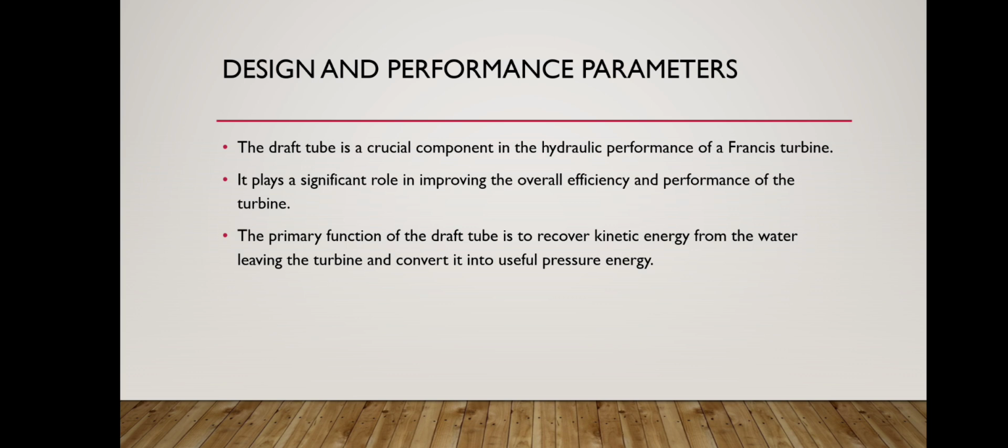Design and performance parameters. The draft tube is a crucial component in the hydraulic performance of a Francis turbine. We all know this, and it plays a significant role in improving the overall efficiency and performance of a turbine. The primary function of the draft tube is to recover the kinetic energy from the water leaving the turbine and convert it into useful pressure energy.